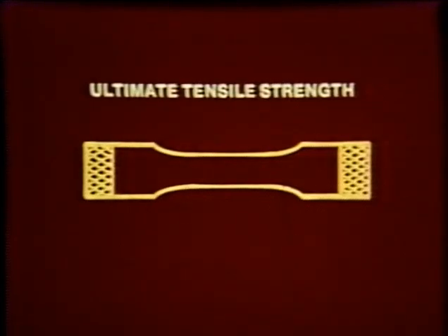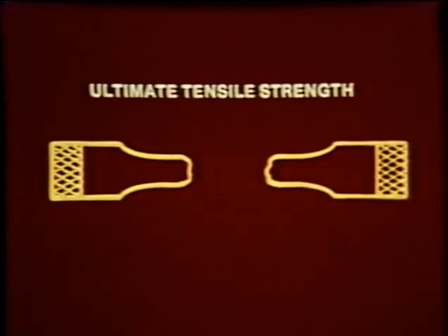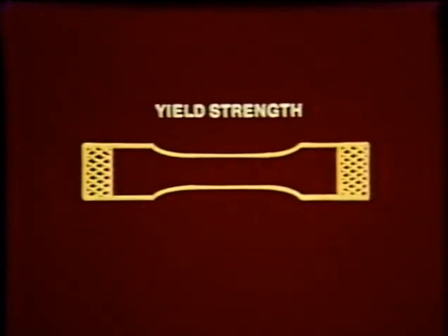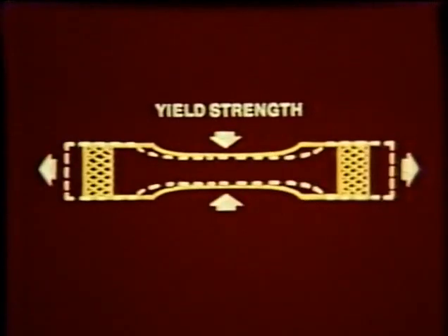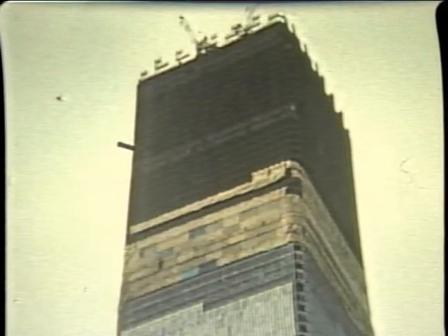One important measure of strength is the material's ultimate tensile strength. This is determined by subjecting weld metal or a welded joint to a pulling load until it fails. The maximum stress developed is a good indication of the amount of load the material can sustain. Yield strength is another important measurement of the material's load-carrying capacity. This is the stress at which the material will permanently change in dimension, usually length and cross-sectional area. This property is an important consideration for structural weldments such as buildings and bridges.